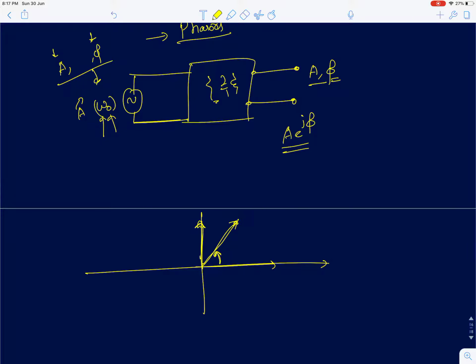It is also used in narrowband communications, when the bandwidth of the signal is so small compared to the center frequency of the carrier that we can approximate it as nearly a single frequency signal, and there again we can apply phasor analysis. But phasor analysis doesn't find applications in signal processing, where a certain band of frequencies is of interest.